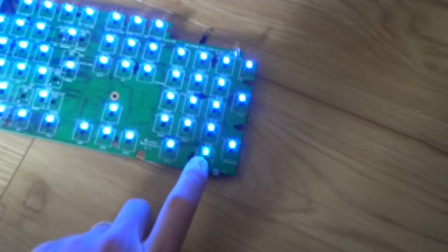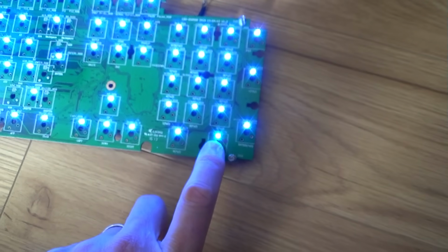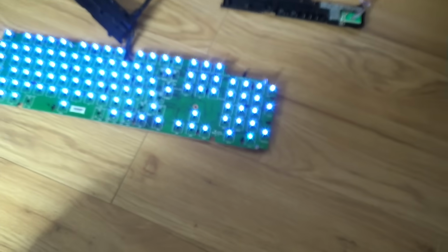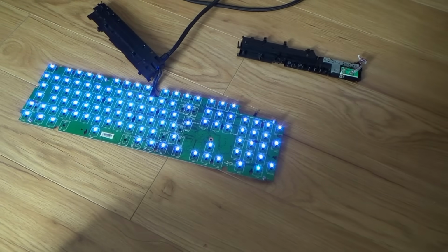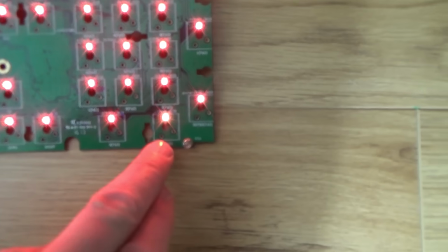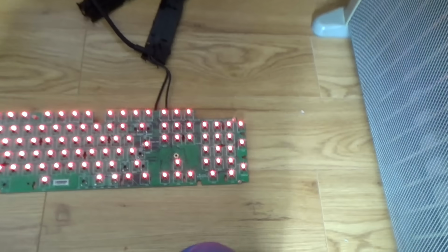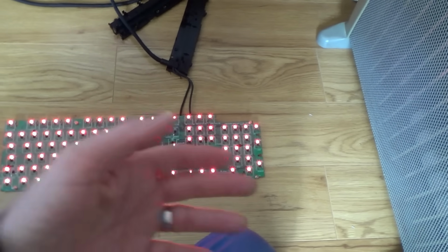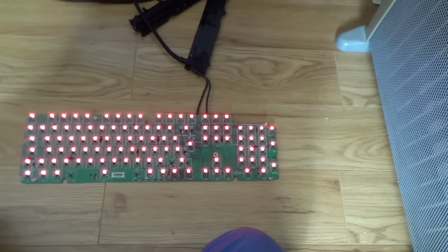So I'm just going to have a little look, see why this is green, because this is one that I've replaced, unless I've somehow soldered the wires together incorrectly. So I might just change that one, see if it starts working. Hip hip hooray! I changed it over. So maybe either the LED was faulty, or realistically, I probably shorted some pads underneath it. Maybe I added too much solder to those ones.